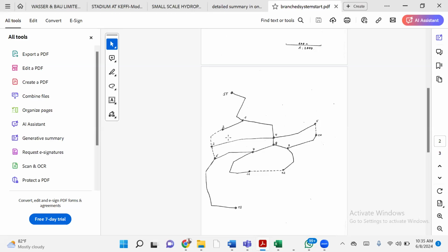Now, what we're doing is a proper standard design. Not so complicated, where you see somebody putting a manhole and just burying it. No, there should be an inspection chamber, a standard. Peradventure you want to do maintenance along section 1 to 2, or along section 4 to 3, you can go to the manhole and lock off the water meter there or the valve there.